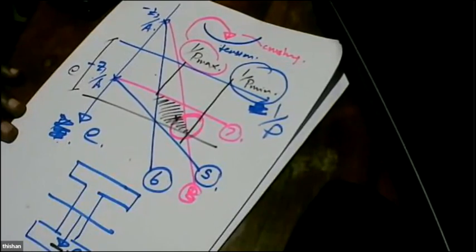So we have enough time to evacuate. But if we go for the maximum pre-stress, it's very expensive because we have to create a massive pre-stress. But the problem with massive pre-stress is it's going to fail in compression, and you will get a sudden failure of the beam. So we always like to use the minimum pre-stress. Is that clear?